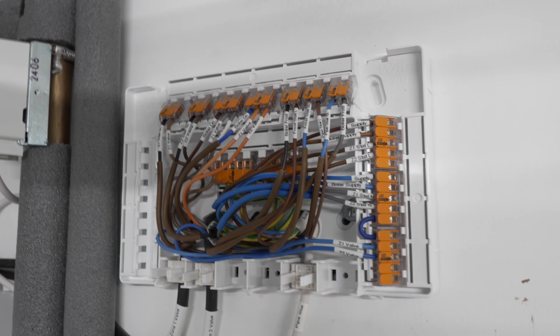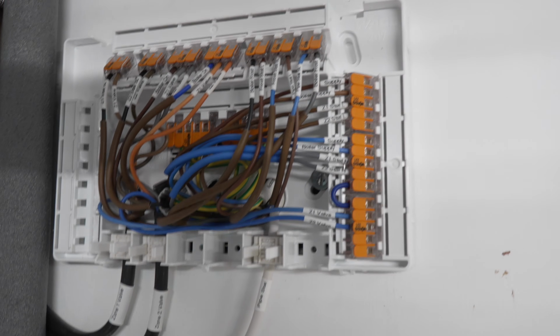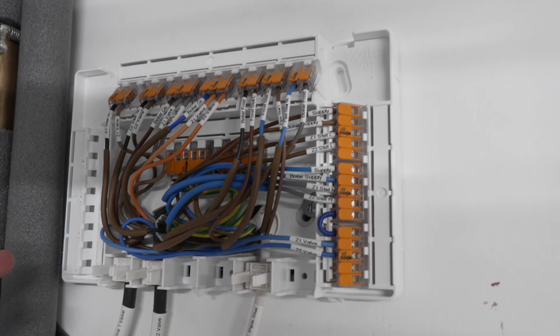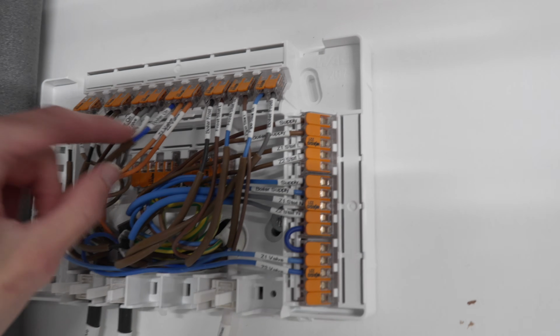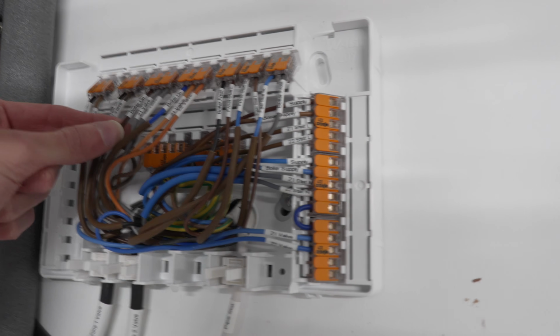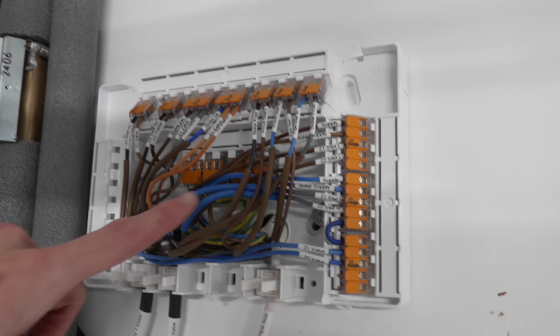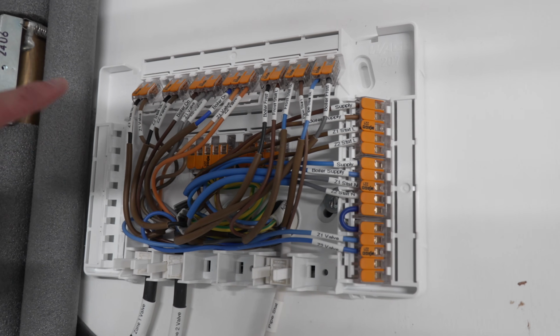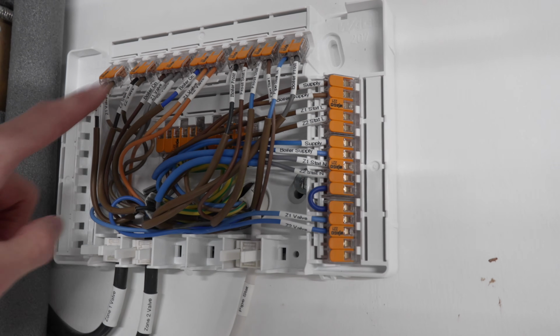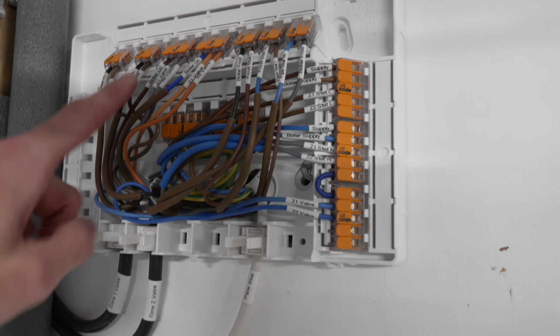So if you had a system like this and it was obviously not labelled like this, that's kind of how you need to go about identifying which wires are which. You'll probably have some wires coming back from your zone valves. Those will probably be connected to some wire to signal the boiler. You could kind of trace that back, work out what is connected to the brown wire that powers each valve, and that is probably going to be what your thermostats are.